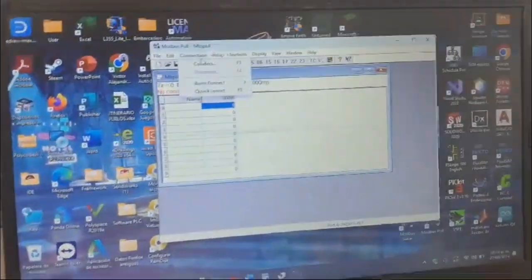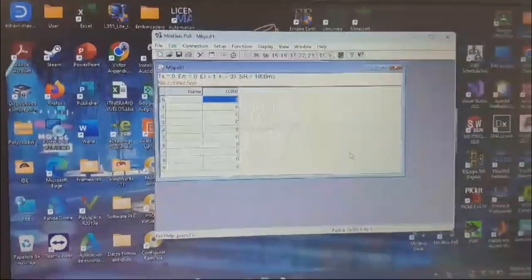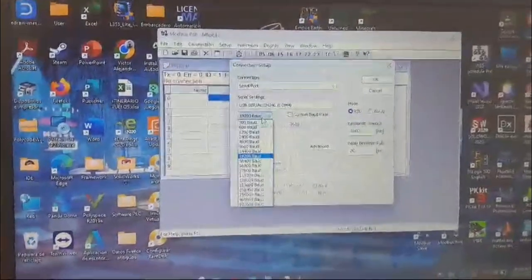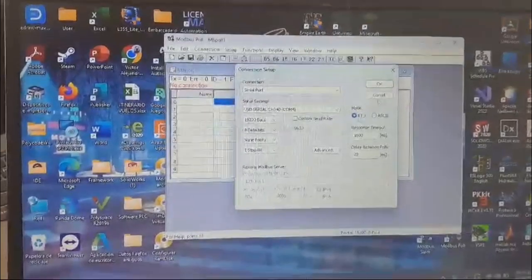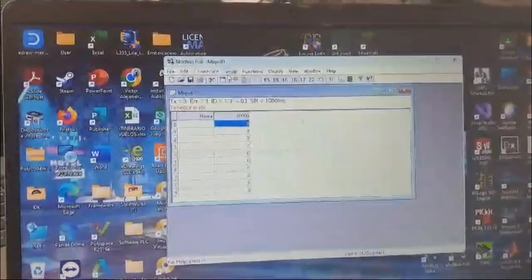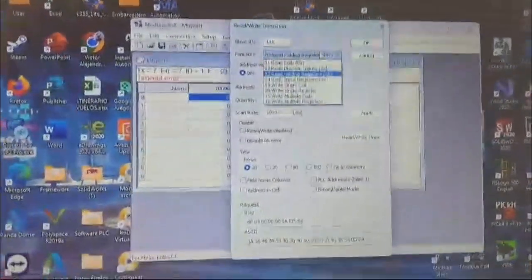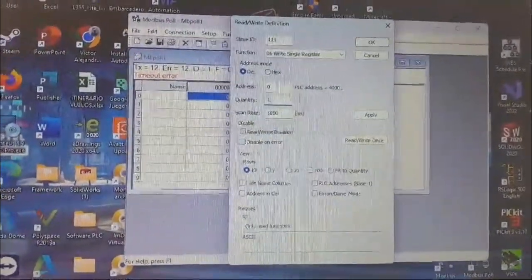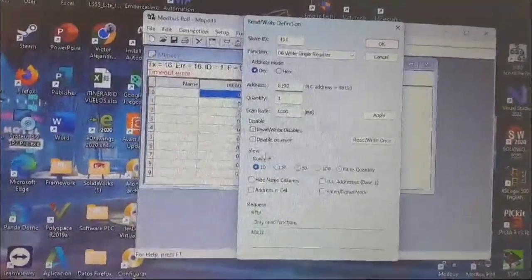Below, we will see the configuration of the Modbus Poll program to be able to vary the frequency of the motor using RTU. As a first step, we physically connect the USB RS485 with the Ethernet cable of the data cables, the minus and the plus respectively, and check the COM port where the USB is detected. Once we have this data, we go to Modbus Poll.